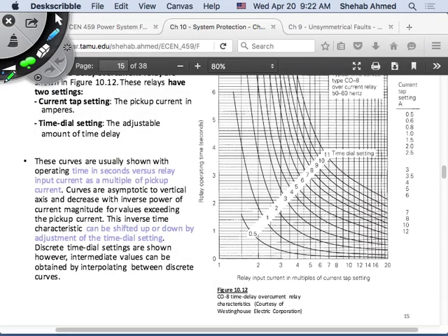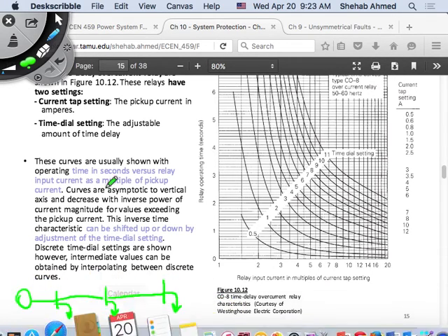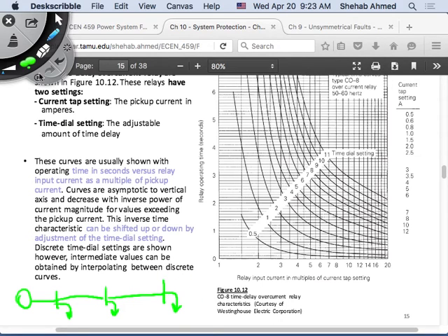If I have a system that looks like this, a source, bus bar, bus bar, bus bar, load, load, load, right? So let's say a fault happens here. How is the fault current going to flow? It's going to flow from here, from the source. What does the fault current see? The fault current sees this impedance, this impedance, this impedance, all the way to here, right?